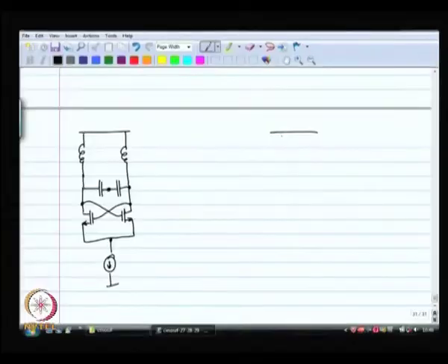So, we need a tank. Wherever you have an inductor, the inductor is really not a pure inductor. So, I am going to model the inductor as an inductor in shunt with a resistance. Now, note this resistor is not intentional. This is something that has come as a result of placing the inductor over there: eddy current losses, series wire losses, copper losses, right. And usually this is my tank circuit.